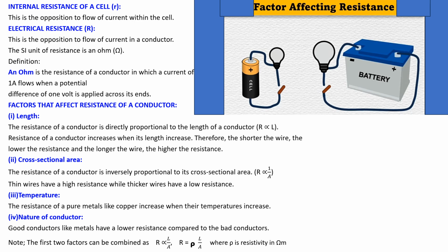For them, resistance reduces when the temperature increases. Why? Because more of the electrons are set into mobility within them, so they conduct electricity better. Remember, we already have some conducting electrons, so increasing the temperature sets other atoms into vibration, and you are creating space within the material. So for semiconductors, resistance actually decreases with an increase in temperature.